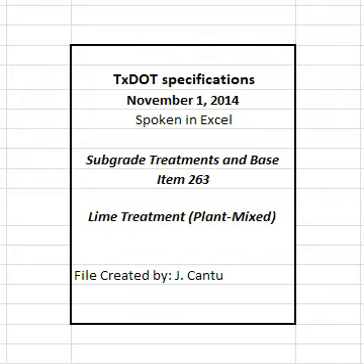2.1 Lime. Furnish hydrated lime that meets the requirements of DMS 6350, lime and lime slurry, and DMS 6330, pre-qualification of lime sources. 2.2 Flexible base. Furnish base material that meets the requirements of Item 247, flexible base, for the type and grade shown on the plans, before the addition of lime.